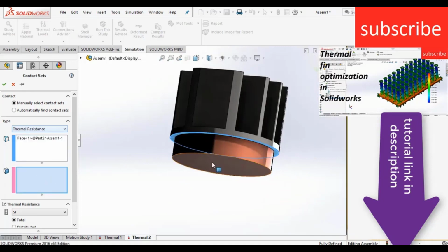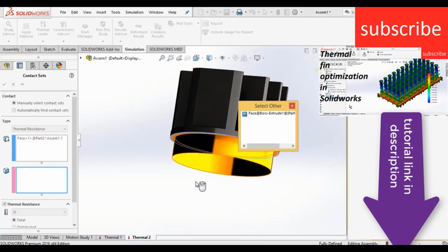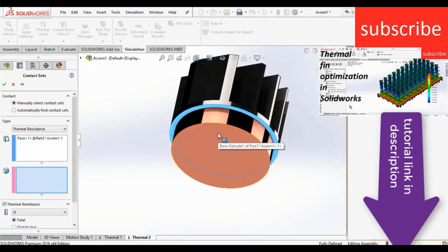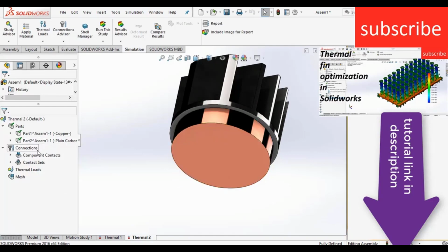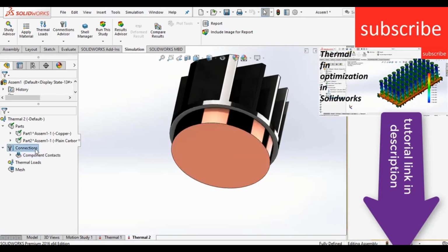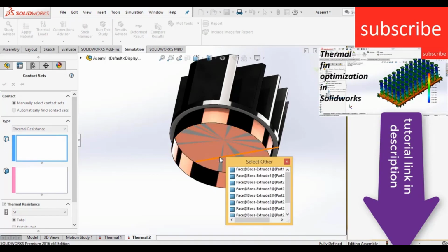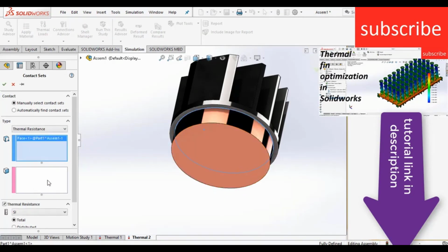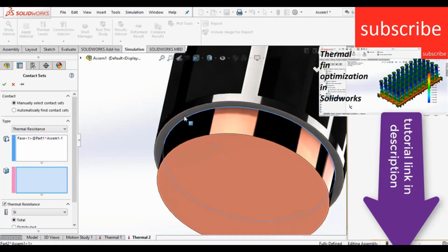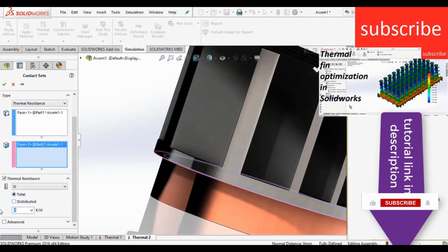Okay, now select this here and right click on select other. Delete contact set, delete it. Right click on contact set, thermal resistance. So right click here, click select other. So as you can see, I am selecting the top part of the chip. So click on the chip and select the bottom part of the fin. Okay, and move downward, select, enter the value of thermal resistance. So you can enter the value as per your requirement.